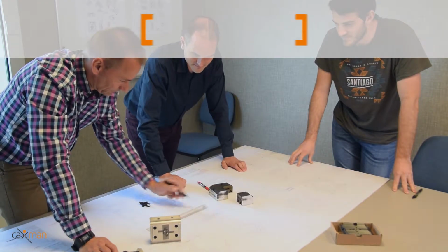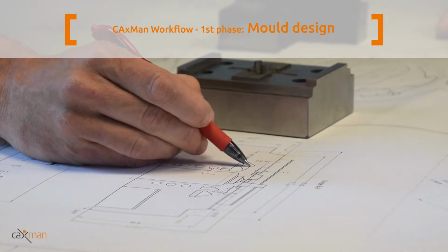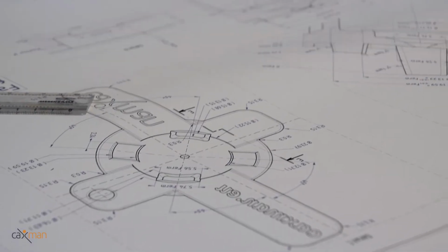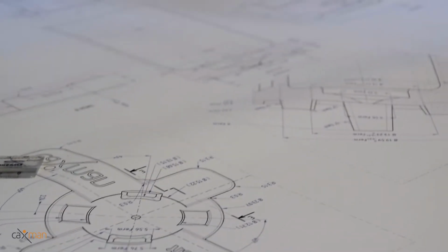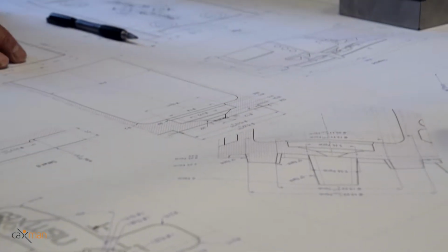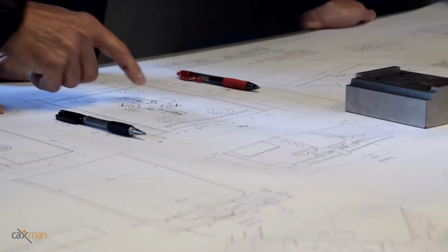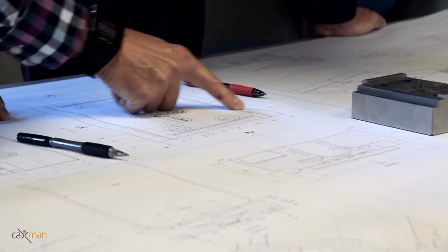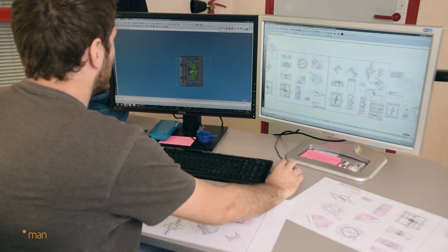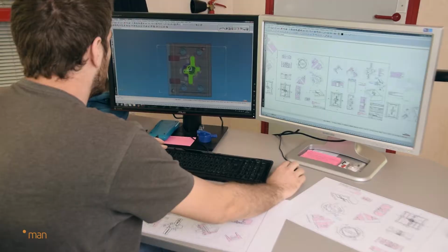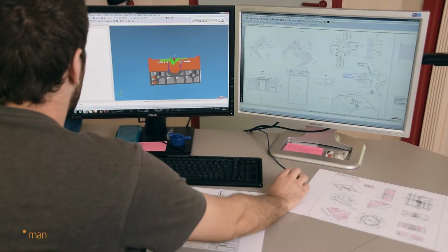The design of a plastic injection mold requires collaboration between two processes, the mold making and the injection of the plastic. The shape and function of each mold can vary due to the typology, the type of plastic, and the number of cavities. The mold can be divided into two parts, the mechanical part, movement, guiding, centering, etc., and the molding part, cavities. Designs need to ensure that both functions are compatible. In the case of multi-cavities, the molded parts to be produced need to be strictly identical.